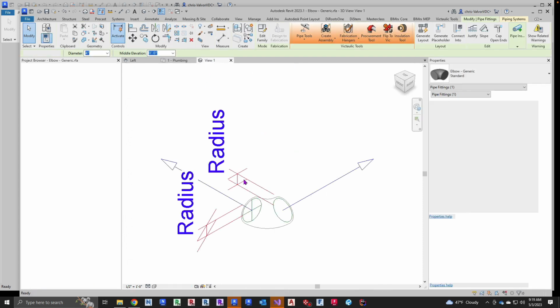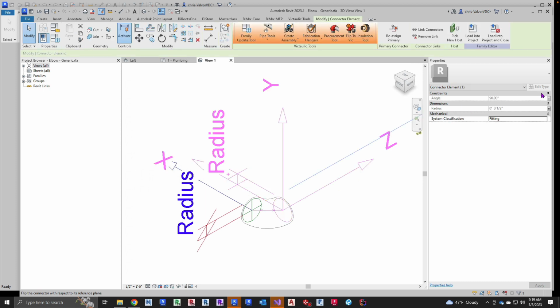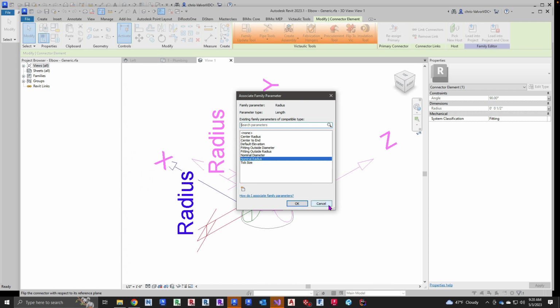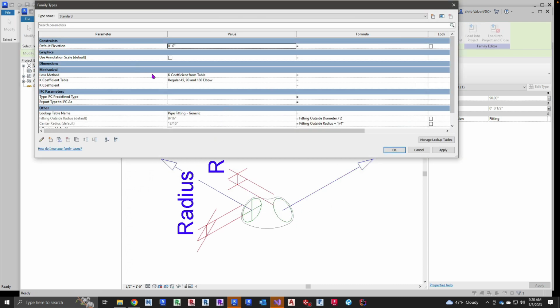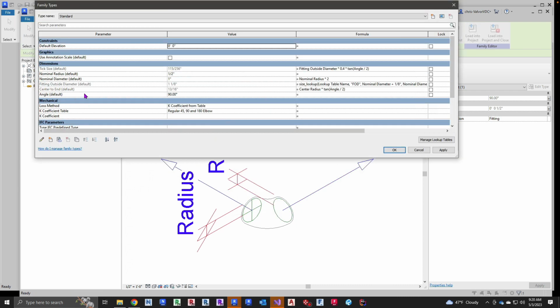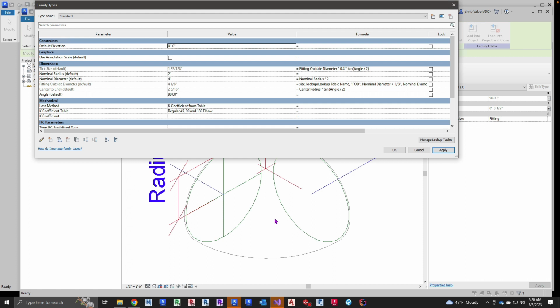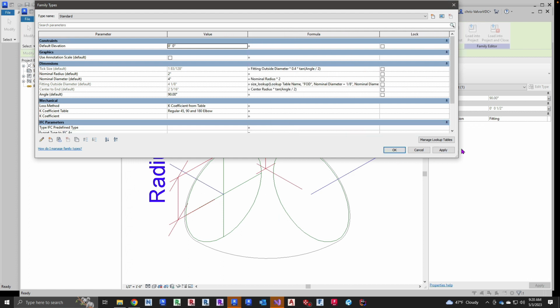So this family is a little different, whereas this links to the radius, which is right there that I couldn't find a minute ago, which is probably because dimensions is collapsed. So if I were to make this a different size, I can make it 4-inch, and you can watch the family move. That's what they call flexing, when you can take a family with multiple components inside of it. This family here is driven by what they call a lookup table.